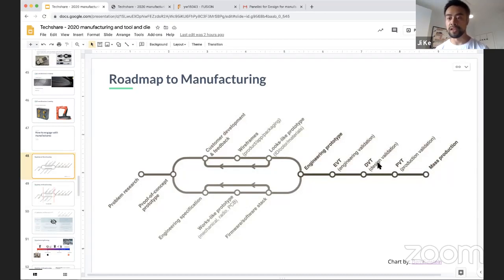The PVT essentially is that everything is ready to go, and then your factory sets up a test production line, and then they start manufacturing, doing a test run, right? So in the test run, you would figure out, oh, hey, there are so many cables, and it's leading to a failure rate because the cable pinches while I snap those two plastic pieces down, right? So we might need to change a bit of the design, then revise the production. Or at what stage do you do QC? How do you increase the yield? This goes into PVT.